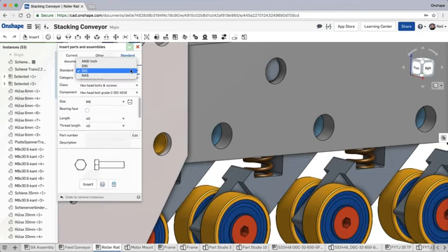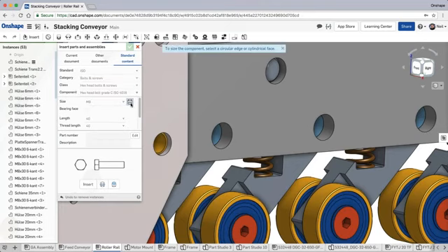There is currently ANSI, DIN, and ISO. Then we can see here we'll include bolts and screws, hex head screws. You can size a screw by picking an edge, and that will get you the correct one. So it's an M6, and then specify what that length should be. So let's go for a 35 thread length.